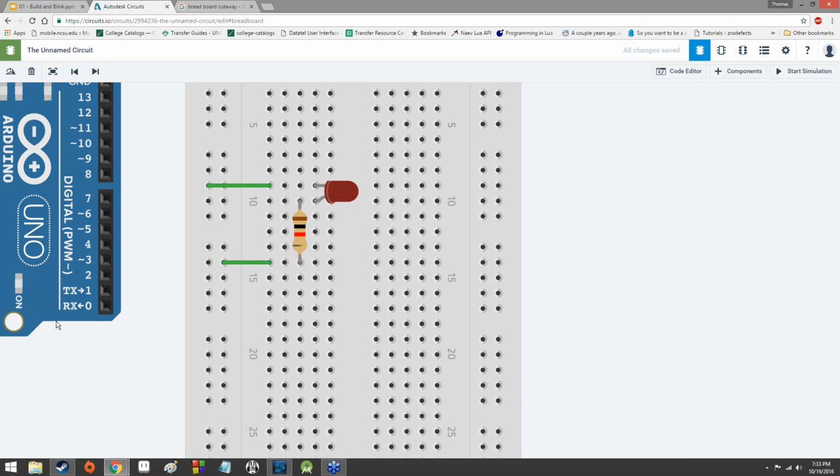A, because I've done this class a couple times before, and B, also you can tell the resistance of a resistor by reading the bands on it. That is true, because resistors are generally too small to print numbers on them. So what they do is they use a sequence of 3 colored bands, and sometimes a 4th one, more often than not now a 4th one, in order to denote the quality and the resistance of a given resistor.